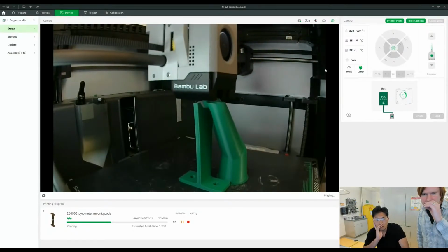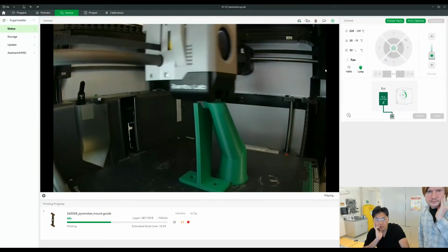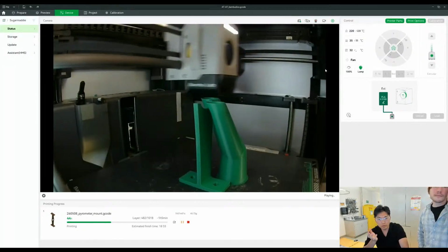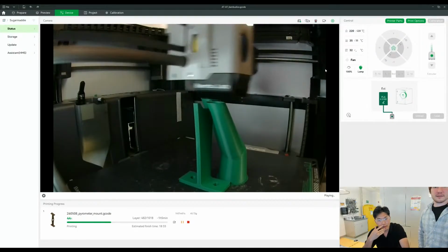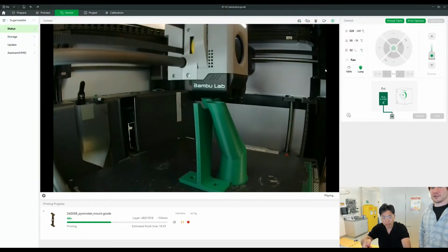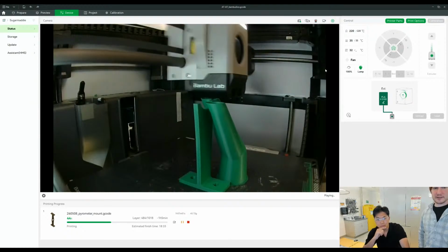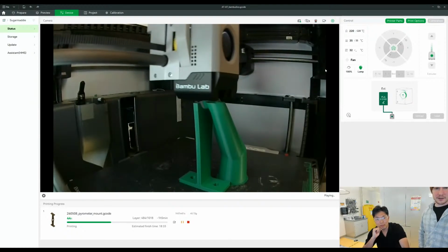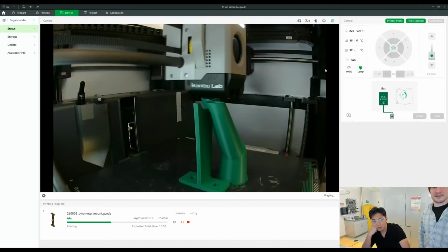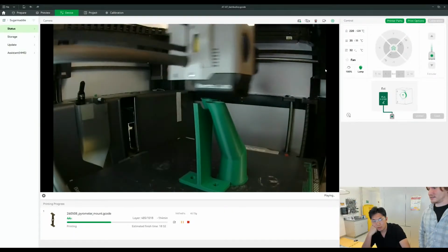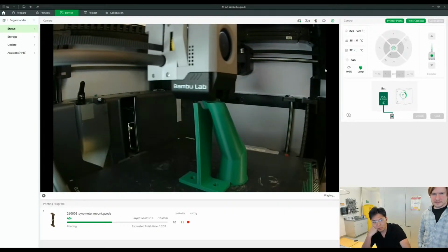So P1 is your 10K to 50K pot for options A, B, and C. Okay, that's just to adjust the input voltage from 0 to 5. That's if you were just using a constant power supply. You could use a potentiometer to vary it, but you could just set it up with like an Arduino that's sending an analog voltage. It doesn't have to be a constant. But it looks like you need to send it the reference voltage to P1, and then you send your variable set point.